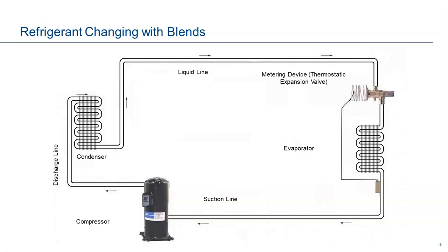Let it stabilize. Let your gauges stabilize to see what you did. They've also got those little vapor converters that you can hook on there. Those are really nice. That changes it over quicker for you from liquid to the vapor. Okay, almost like a piston device. We start the system up.